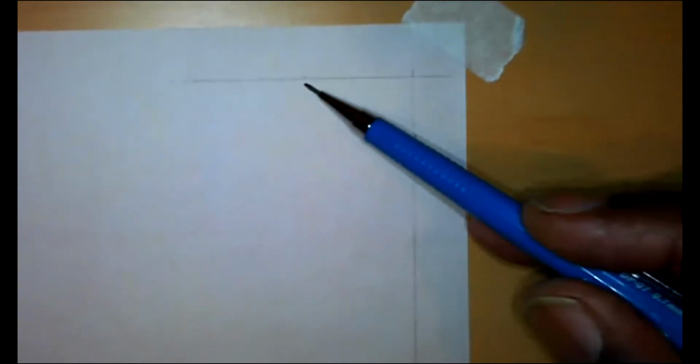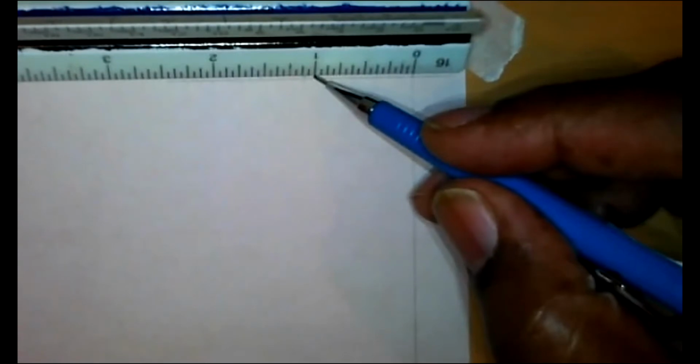Okay. So now the title block is an inch in width. So I'm going to come over here at this intersection right here. You can see that at the intersection right here. Then I'm going to come over an inch. Give myself a reference point. Get my 30-60 triangle. Line it up with that. Good. So that's the width of the title block.